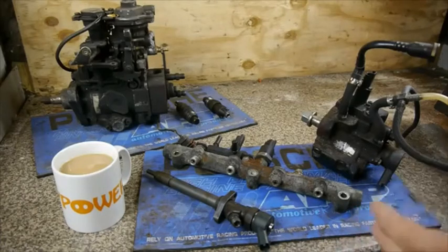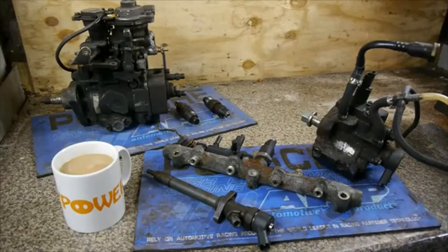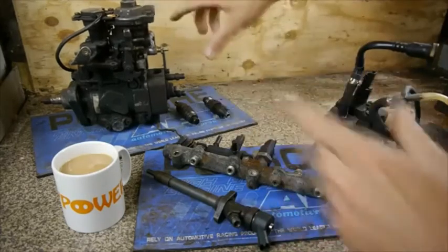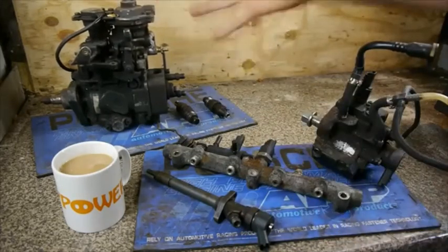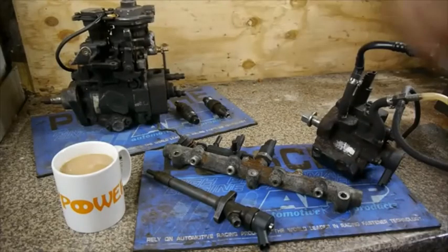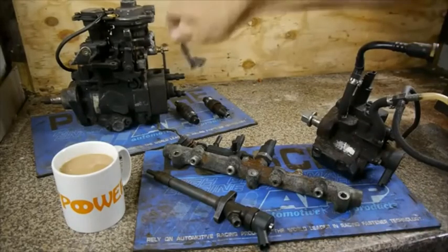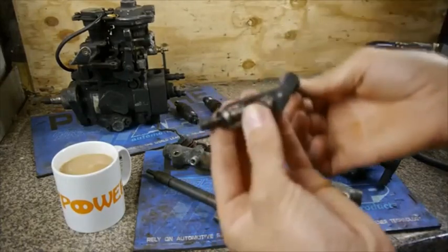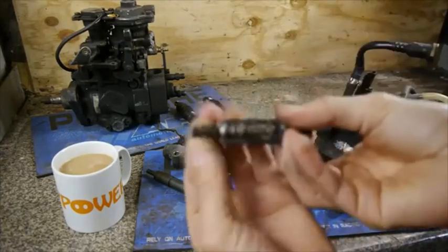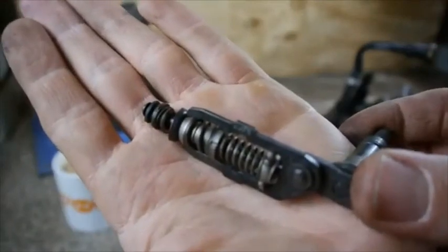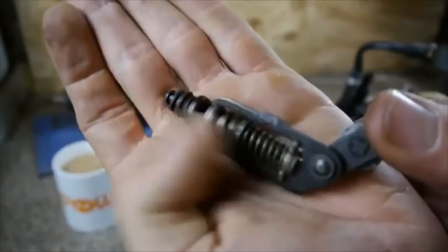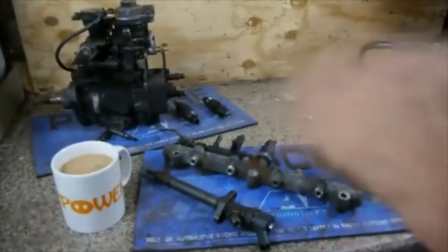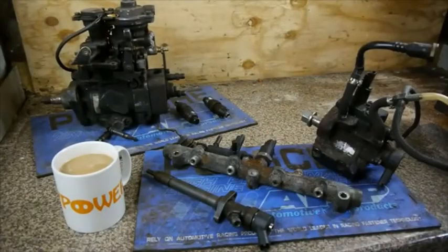Now this is where the differences again in control happen. While an ECU is required to control all this, some of these systems later on had ECUs, hence there's a little sensor on the top, but generally speaking these were completely mechanical. For instance, inside the top of this is the governor and the throttle, and there's a bunch of springs you can see which control everything. So in comparison to ECU control, it's all about springs, and you can modify these little things for them to rev harder. It's just all about nuts and bolts, as opposed to this where it's on the laptops.